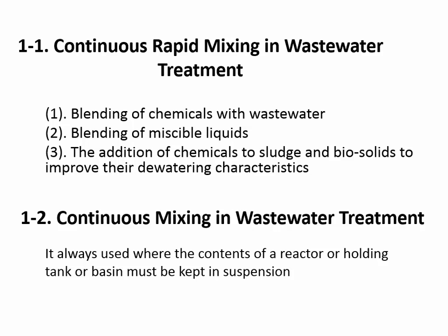Usually most mixing operations can be classified as rapid mix or continuous mix. The difference is, if the detention time is less than 30 seconds, it is the rapid mix. But if the detention time is longer than 30 seconds, it should be the continuous mix.